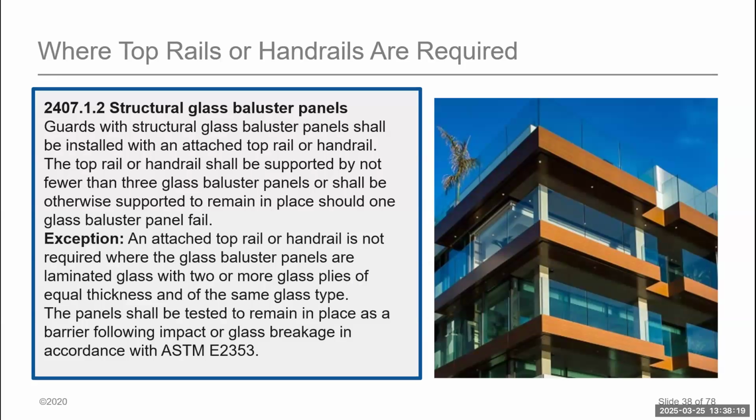But from a code perspective, they want the top cap because it provides some loading benefit to the system. But if your system has been tested or has an industry accepted report, like an ICC report, where it has been tested without a top cap, then you are not required to have a top cap. And that testing standard is dictated and written by ASTM 2353.